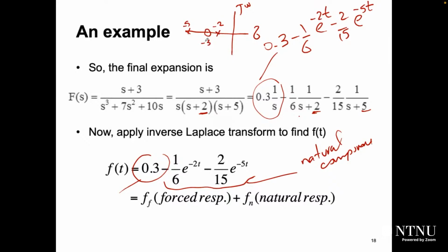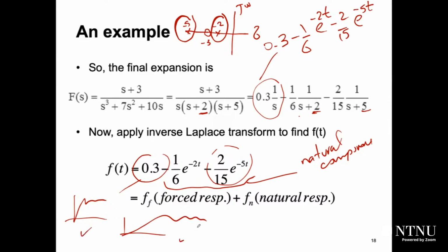As you can see here, the exponential part which is generated from minus 5 will decay faster than this one, right? So that part will decay faster than that part. So when you go far away from the j omega axis, your system will be faster, because the exponential part decays faster, which means your system will be much faster, correct? We can also have an equation in that part. So we have a response like this, and maybe something like this, and another response like this one. So which one? Is it this one or this one? According to your pole locations.